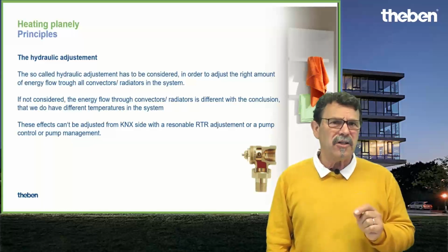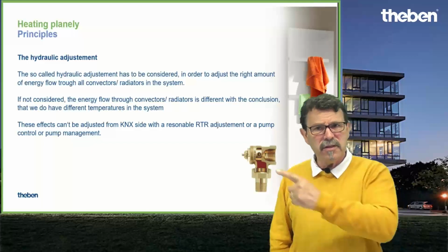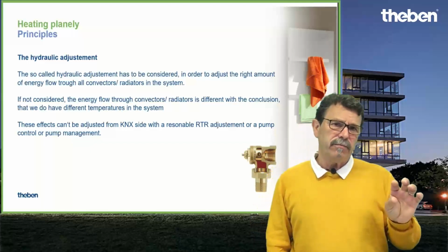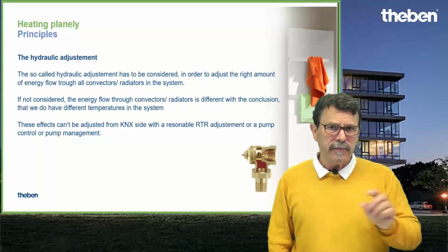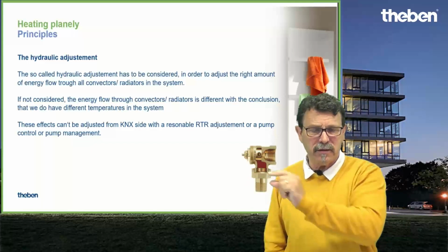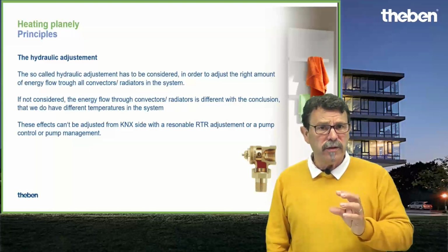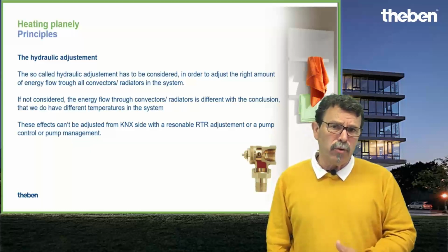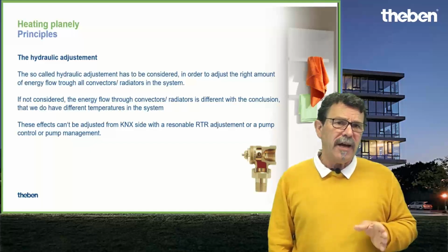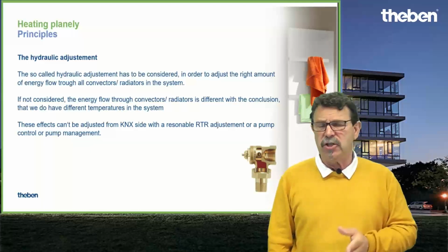This is mostly hardware. For instance, hydraulic adjustment. This is a valve which you see here, directly installed on a radiator. Here on this side the valve is installed. You have a small ring with a pitch, and upon it you put the thermal valve or motor-driven valve. There is a small screw, and with this screw the heating specialist has to do the hydraulic adjustment.